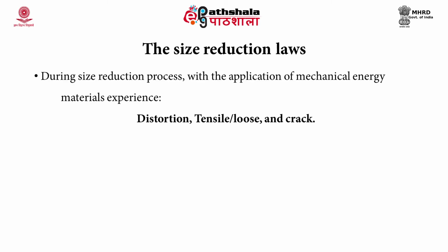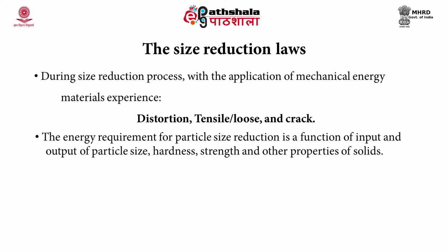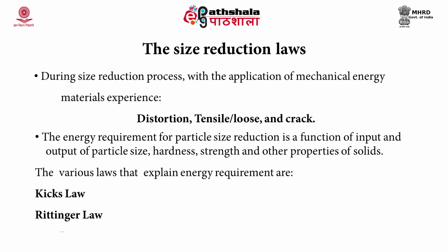During the size reduction process, the particles experience mechanical energy, due to which they get distorted and become tensile or loose, and further they crack. After that, they are broken down into smaller pieces or finer particles. The energy required for particle size reduction is a function of input and output particle size, hardness, strength, and other properties of solids. Basically, three laws govern the size reduction process: Kick's law, Rittinger's law, and Bond's law.